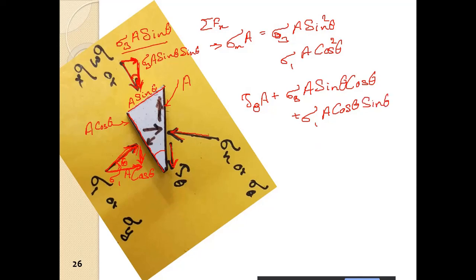Similarly if you have a shear stress here, tau, just like this, the force will be tau into A sine of theta. That is the force.